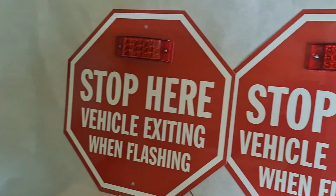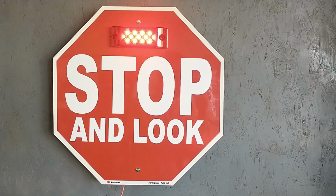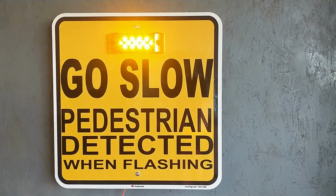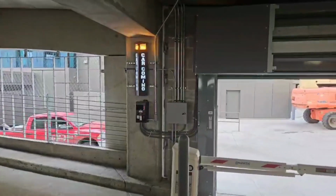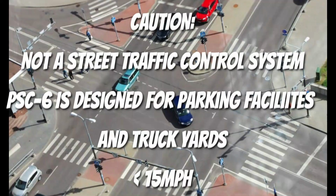You can also use the PSC6 with a combination of our warning signs to push visual and audio messaging. You can even integrate pedestrian traffic control into the system to stop traffic while giving signals to pedestrians to cross safely. The PSC6 is not intended to be used in street speed traffic applications. It is intended for traffic that is typically 15 miles per hour or less.